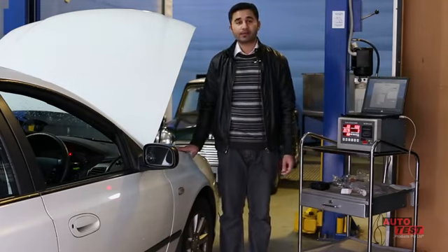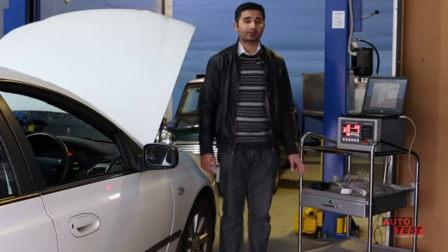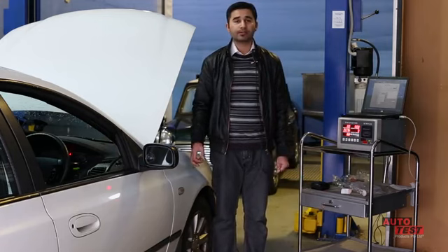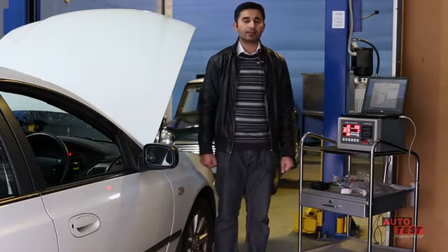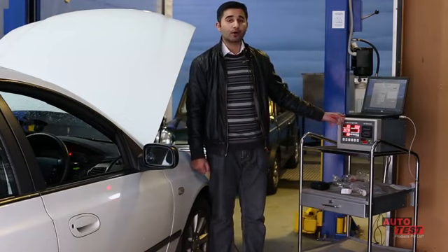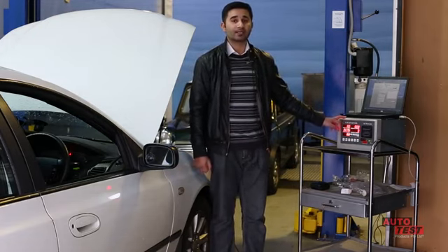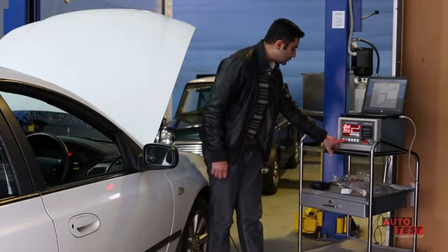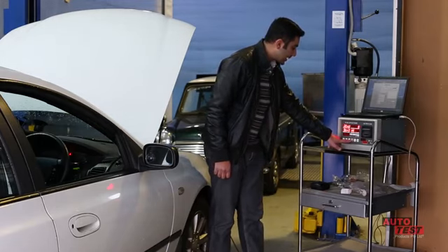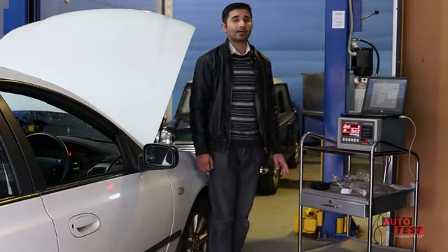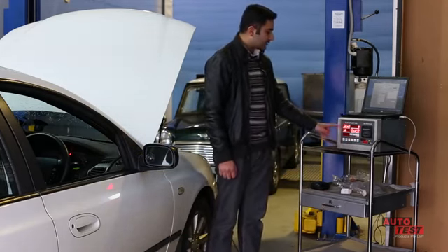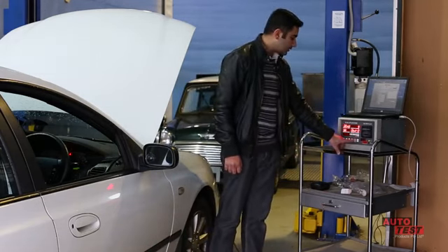Now the car is running, the smoke meter is running, and the gas analyzer is running. They're all running. The OBD connector we have connected already in the vehicle. What we're going to do now is enable the Bluetooth OBD on the gas analyzer while the car is running. For that, we press menu and then scroll down to menu number 9, where it says BT OBD2. When the gas analyzer displays this on the screen, press OK.